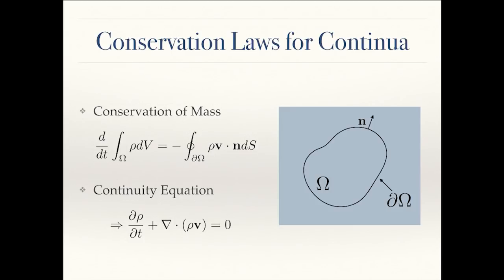So now we apply a couple of calculus theorems that we will see a lot. Not in this course, but if you do physics-based animation, you'll see them a lot. One of them is the divergence theorem. That's going to convert the surface integral over here into a volume integral. The other thing is bringing this time derivative under the integral, which we can do simply when this region is fixed, as it is in our case. And those two things we rearrange a little bit, and we get what's called the continuity equation.